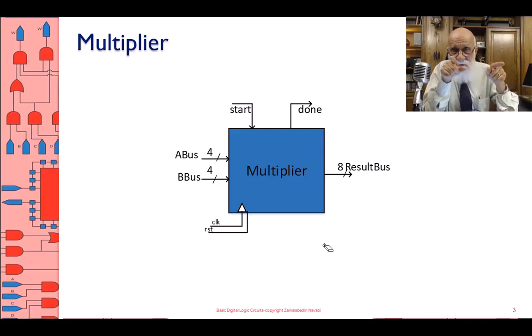But then I know that the result will be an 8-bit result because B is 4 bits, A is 4 bits. And therefore, I put B in an 8-bit register. As I'm decrementing A, I'm adding that 4-bit to itself, to itself, to itself. So I have an 8-bit adder. I have the partial result that keeps getting added to itself. And then I have the counter. So that's all there is to it. That is absolutely all there is to it.